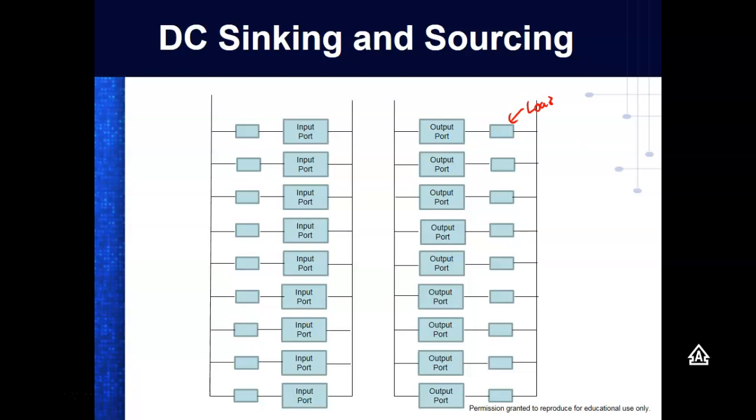What we find out real quick is that PLCs do not do away with relays. PLCs can only output, rule of thumb, around 2 amps per output port. That wouldn't be enough to run a motor, but it would be enough to bring in a relay that runs a motor, right? Does that make sense? So they haven't done away with that.